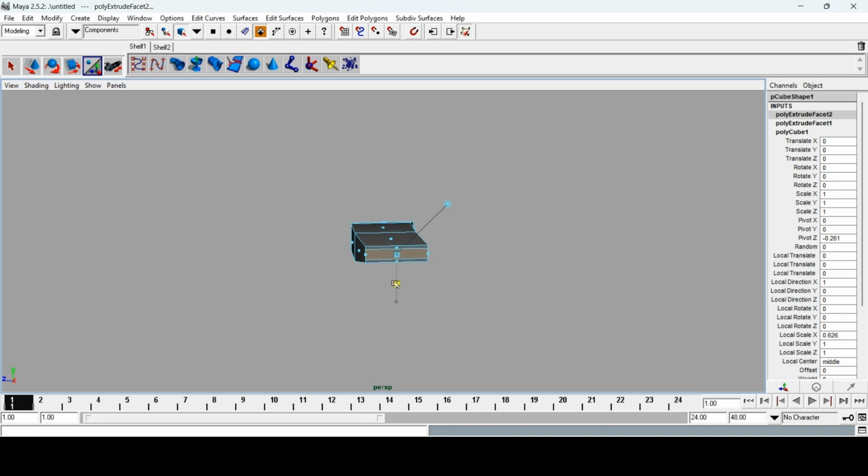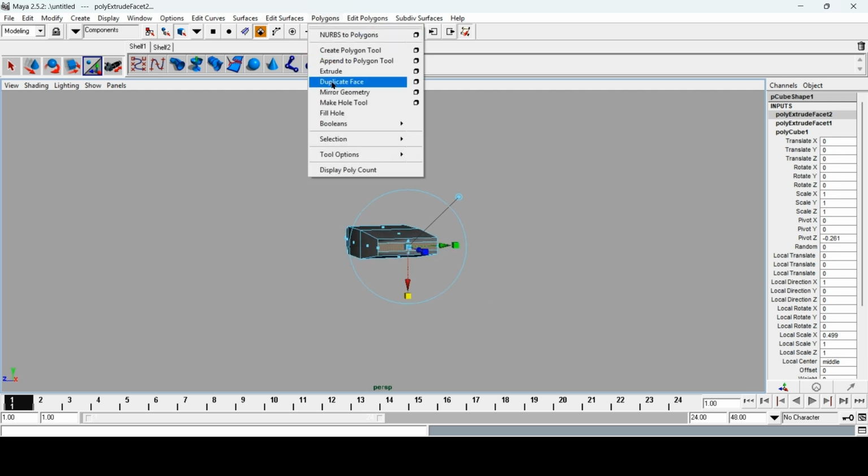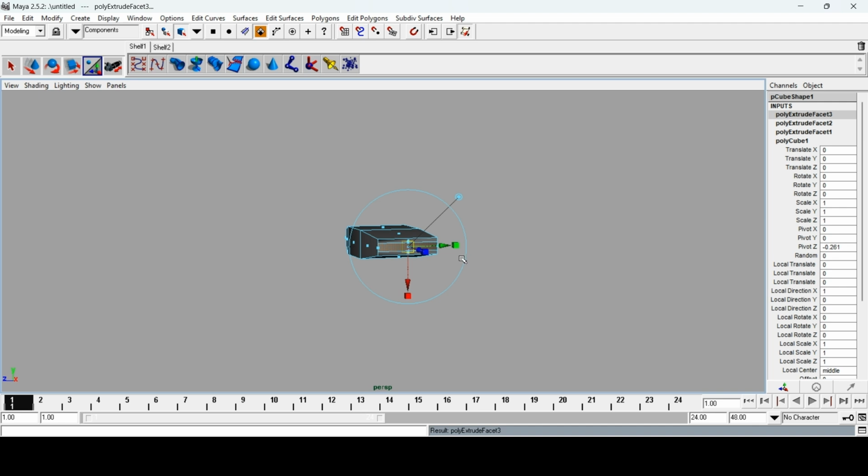Okay, let's see. Now click on this box. As we can see the lines are appearing, closing. At some point we can extrude it. Okay, now I think this line is perfect for wings. Just click on extrude again so that only the selected face is extruded. Now drag it outside using the blue arrow.